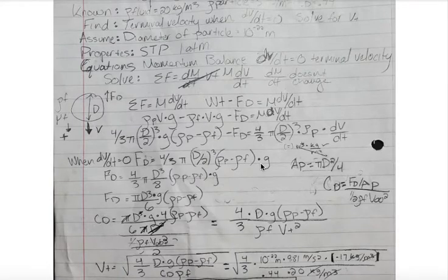So right away we could cancel. We know that mass doesn't change, so dm/dt goes to 0. So we say the sum of forces equals m dv/dt. The sum of the forces is weight minus the drag force. The weight includes the weight of the particle and the buoyant force, which is present right here, and then the drag force. With all that in mind, we can factor out the volume and get just our densities, and then we can factor out a volume multiplied by density to get a mass on the right side.